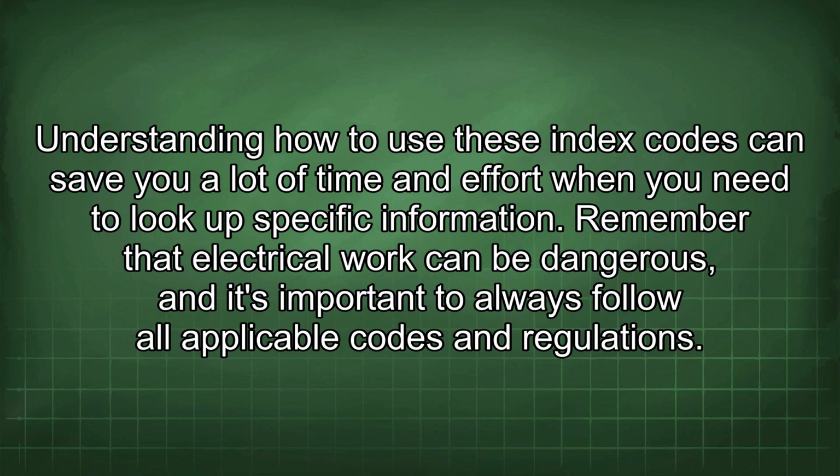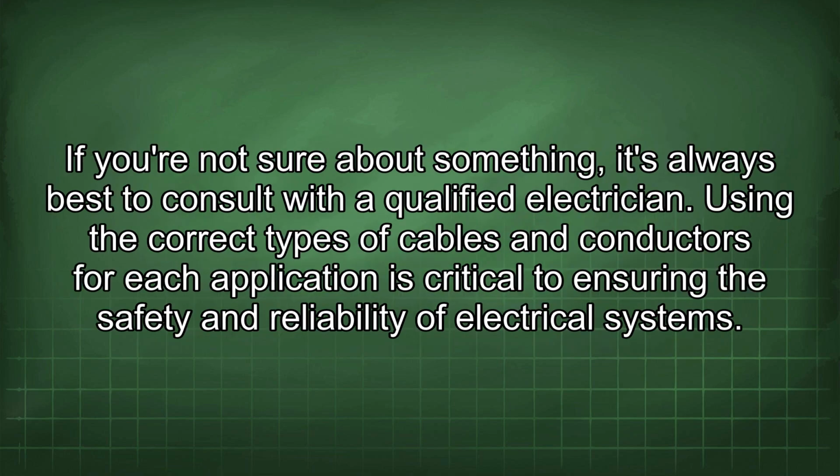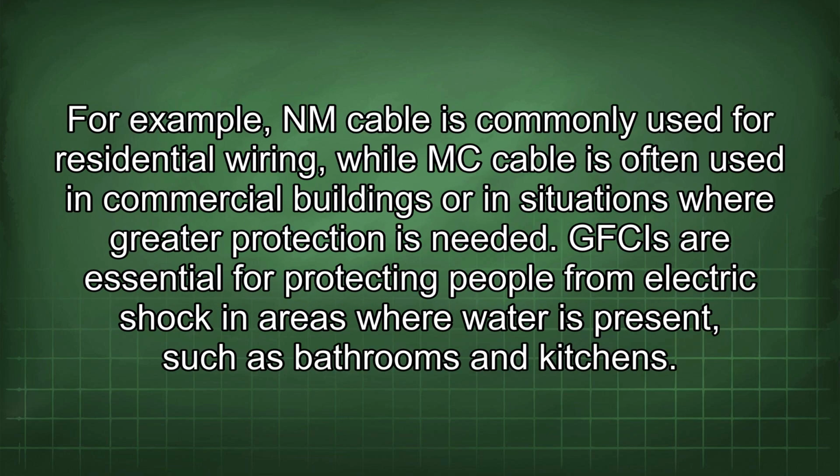Remember that electrical work can be dangerous, and it's important to always follow all applicable codes and regulations. If you're not sure about something, it's always best to consult with a qualified electrician. Using the correct types of cables and conductors for each application is critical to ensuring the safety and reliability of electrical systems. For example, NM cable is commonly used for residential wiring, while MC cable is often used in commercial buildings or in situations where greater protection is needed.